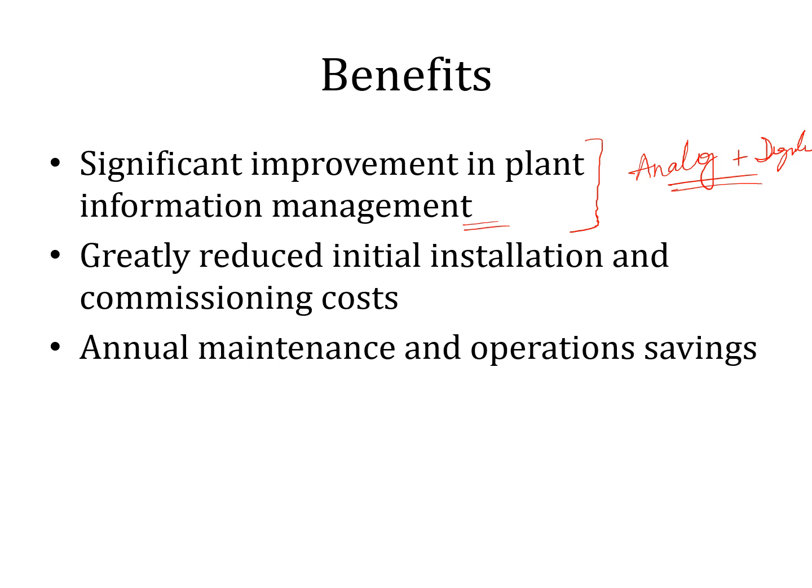We could come to know which particular equipment is responding, which is not. We can reconfigure them, and due to this the installation cost was also very less. The reason was we already utilized the previous existing 4 to 20 milliamp current loop, and since we can do the diagnosis in real time, the annual maintenance cost has also been reduced.